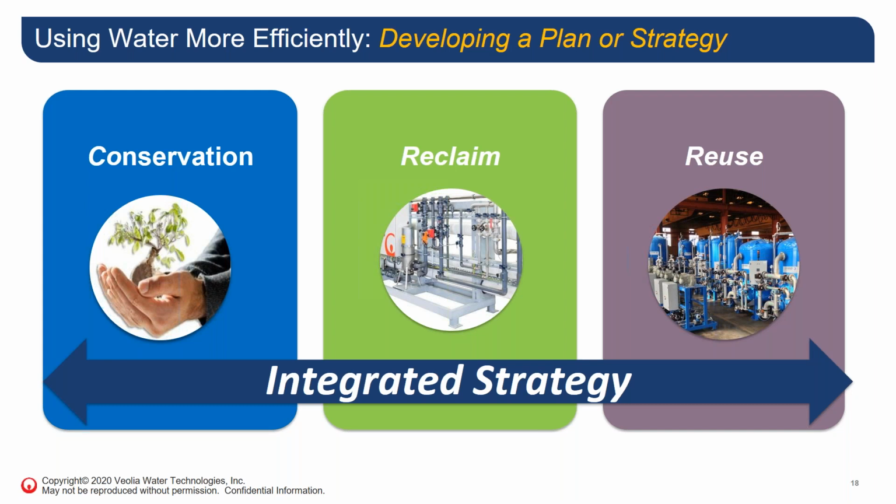These are areas such as improving or increasing the cycles of concentration in your steam boilers. Likewise, cycles of concentration in your cooling system. The operation of utility pretreatment equipment. Work on things such as regeneration schedules and the efficiencies of those regenerations. Production process filtration backwashes and rinses. Housekeeping and cleaning procedures, which utilize a lot of water. Production quenching, rinsing schedules out in the plants.